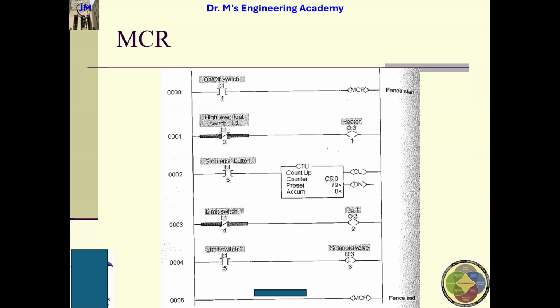So for the count up and the done bit, those are non-retentive outputs. So when it's off, will it reset the counter back to 0? You will reset. Yeah, if that one is reset, this one will be reset. That means this guy will not work, no matter how you press it. So whatever value the count up is on, when the MCR is activated, it'll go back down to 0 or the default. Yes, this guy will be deactivated. Okay, that's a good question.